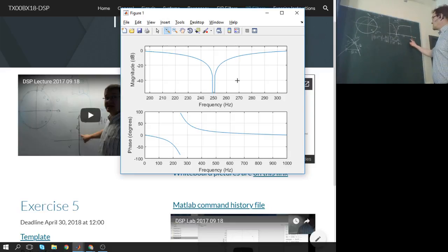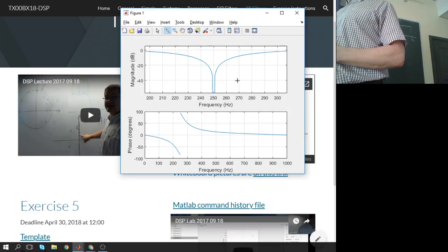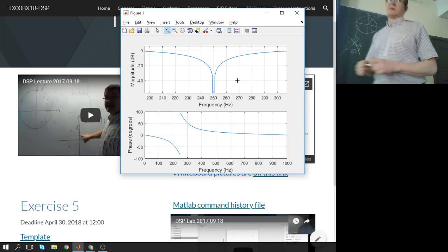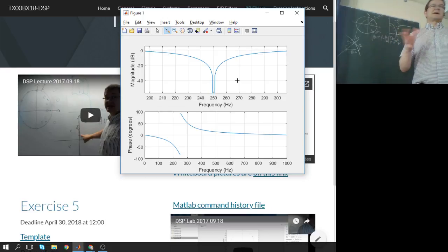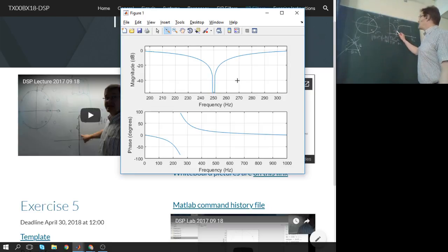But where you have the jitter is usually on your sampling clock, on your microcontroller, unless you use a real crystal oscillator outside. Then you need to have some sort of calibration on it, or measure where your highest noise peak is and adaptively follow that frequency and tune your filter exactly to that one.